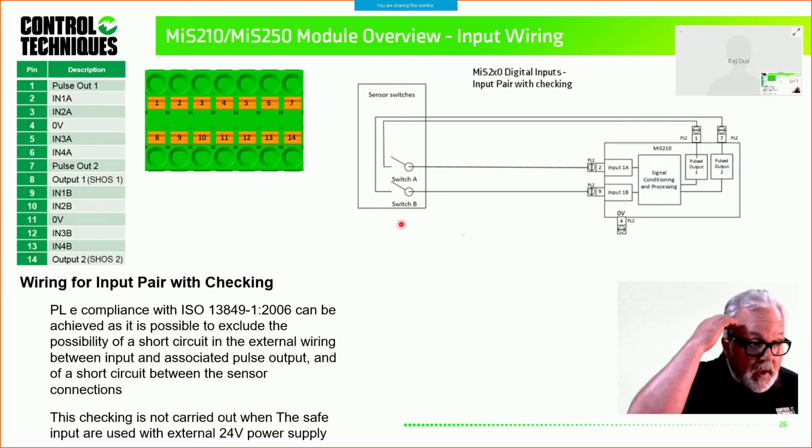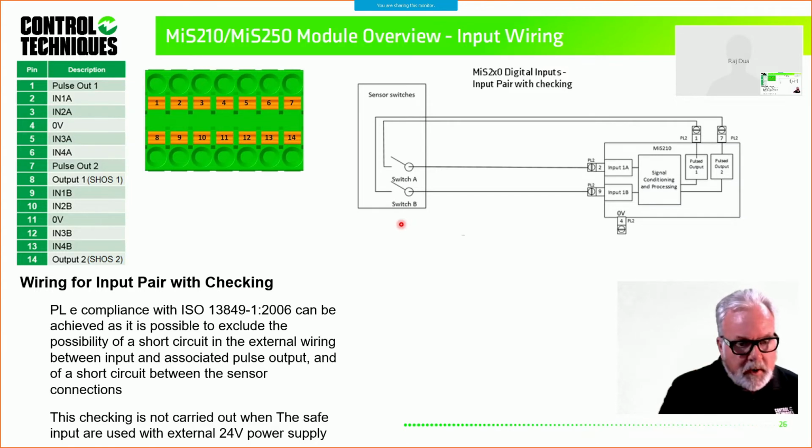A big part of machine safety is redundancy. So that is why there are complements provided for the two digital inputs. Yes, it would appear that there are 4 inputs, but they are treated as pairs. So they both must be true in order for the safety circuit to acknowledge their presence. And I'll show you what happens otherwise tomorrow. But they operate in pairs.